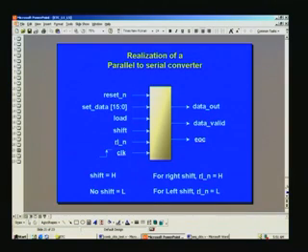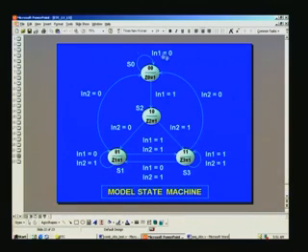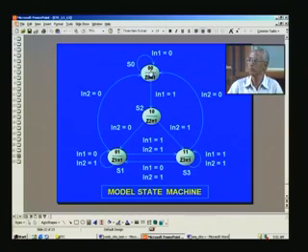We also saw a model for a state machine, that is what is here, and you have Z0 to Z3 states, and these are all the outputs. For example, this is only a simple output to indicate in which state you are in, either in S0 state or S1 and so on, and based upon two inputs, in 1 and in 2, you can make the transition from one state to another.